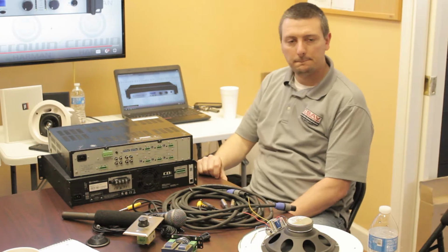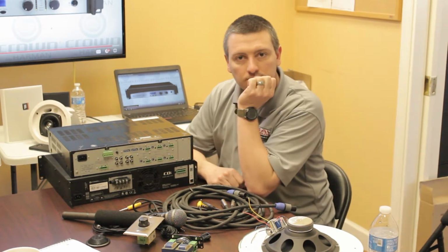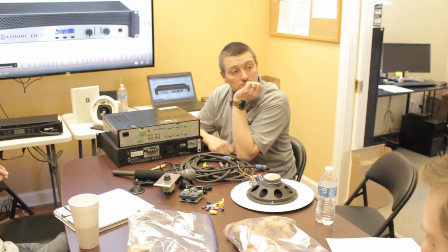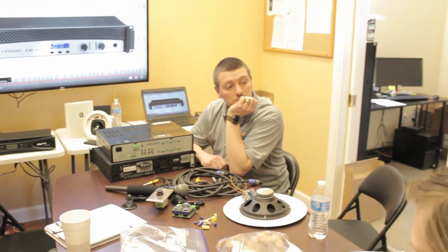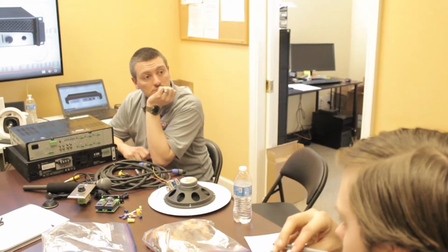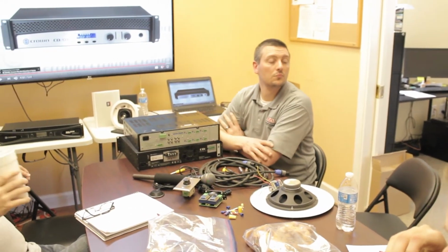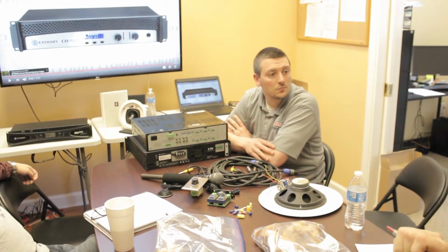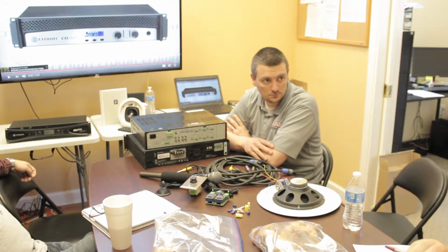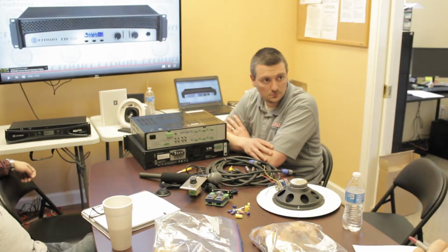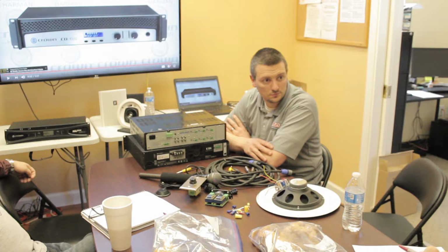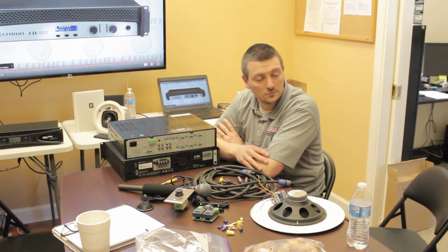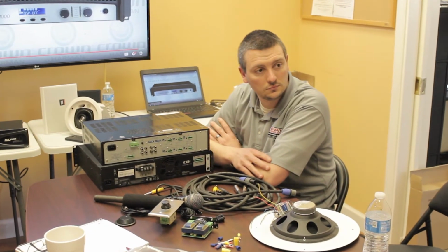John, you had a case this week where you had to re-terminate a touch panel because it was all locked up. Oh yeah. It was in Bayshore. In room B, the Aurora panel was operational, but wasn't controlling anything. So obviously I restarted it. Didn't happen. As a last-ditch effort, I pulled it off the wall to look at the back of the connection, and just reseated it and restarted it from there, and it came back and was controlling. I don't know if it was a bad RJ45 connection. I just re-terminated it and plugged it back in.